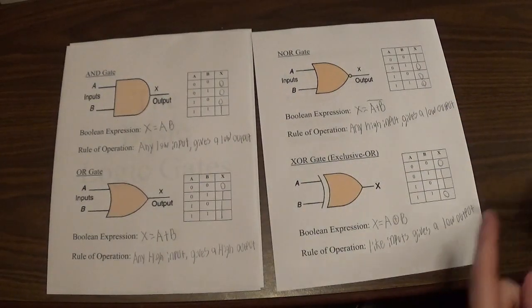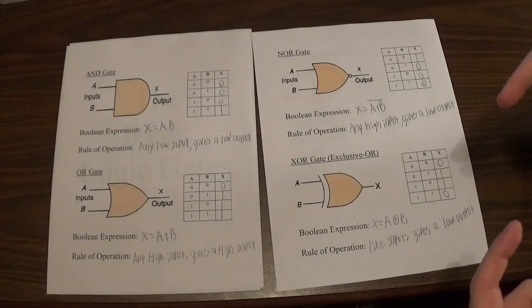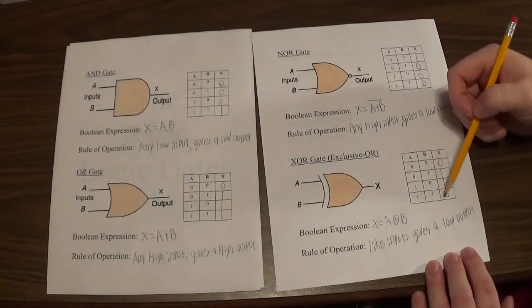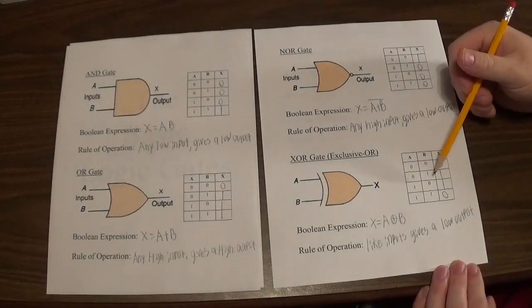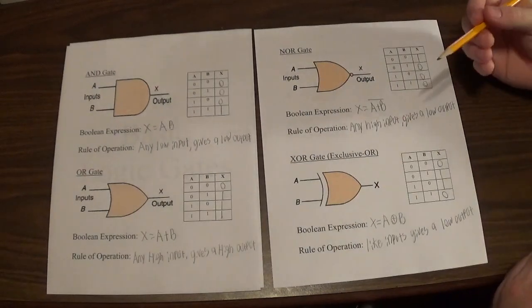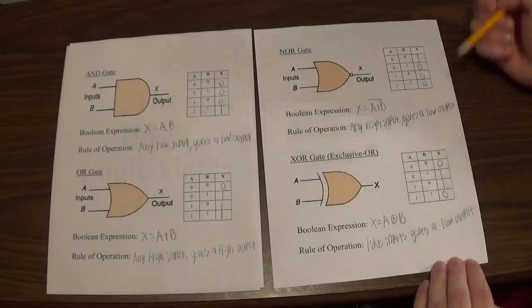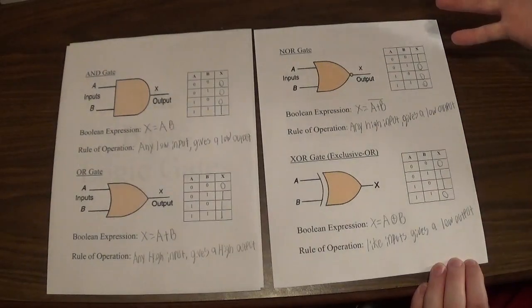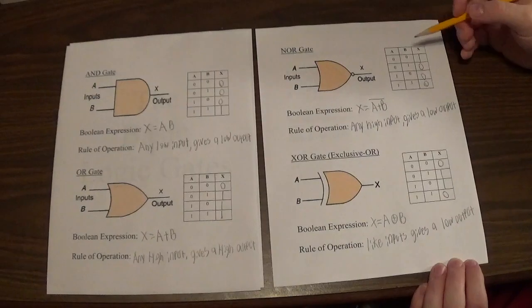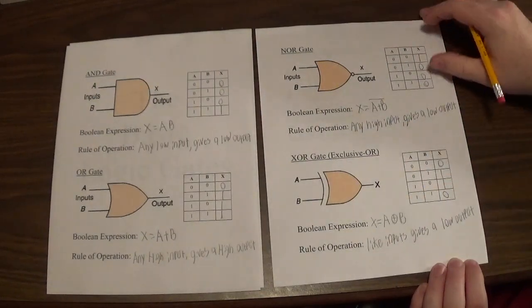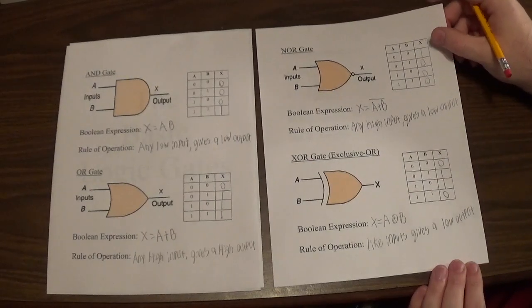So you could use this where you have two different switches or sensors monitoring something, and as long as they're both in agreement, as long as they're both off or they're both on, then the output is 0 and everything's fine. But for some reason, if one of them was to be off and the other one to be on, so they don't agree, so if they're measuring the same thing but one is getting a different reading from another, then the output becomes a 1. So that could sound an alarm to let us know that there's something wrong with our process. So that's the kind of application this is used for. So it's very specialized. All right, so that is the exclusive OR function. Like inputs give you a low.